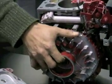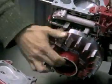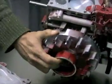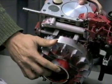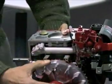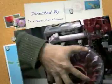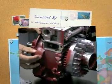At this point, the crankshaft is still rotating, so it's going to start pushing the exhaust air out, and the cam will then open the exhaust valve, and the exhaust valve will release all the gases out and back to the tailpipe of your car. So these are the four strokes of the engine, and all four strokes are controlled by the rotation of the crankshaft and the cam, which controls the valves.